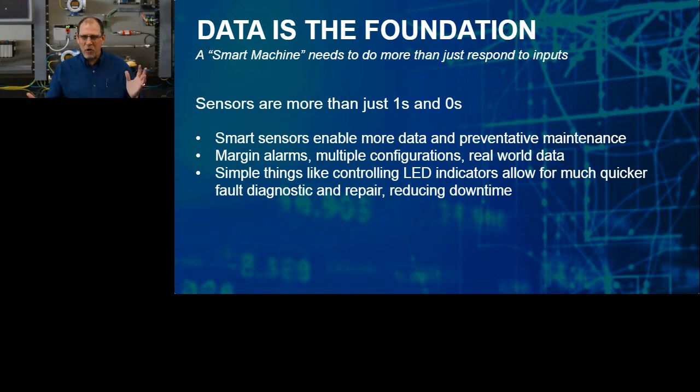What sensors always did in the past is, something would go by a sensor and it would trigger it, which would make something happen. One of the first projects I worked on early in my career, we had mechanical cams, and this rotary machine would come past, trip a mechanical cam, and have something happen. Well, the reason we wanted to change it was every time we wanted to do a new setup, you had to stop the machine and adjust this mechanical cam. There was a lot of tweaking of this.